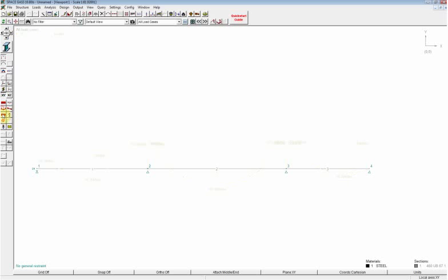So yeah, underneath that again, to the right of it is your shear force, and bottom left is our reactions. So we have a moment going the anti-clockwise direction on point 1, and because it's a roller joint on all the other ones, there are no moments generated. Also see how SpaceGass keeps ghost images up? We can get rid of those. If you just double click on view members, it'll just clean it all up for you. Okay, so that's that.